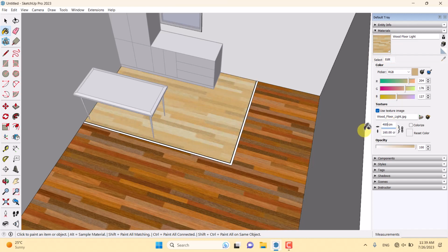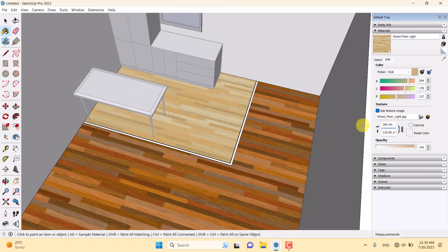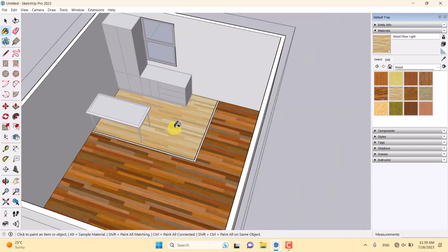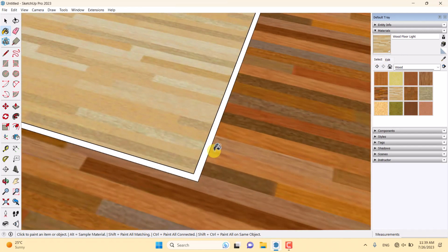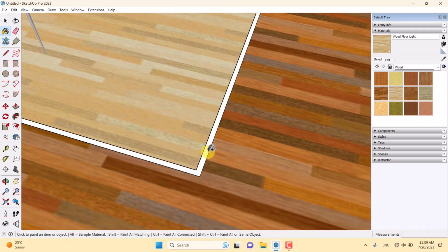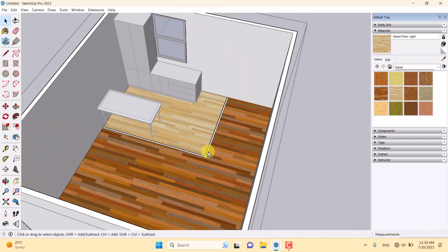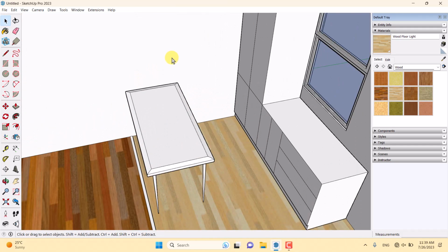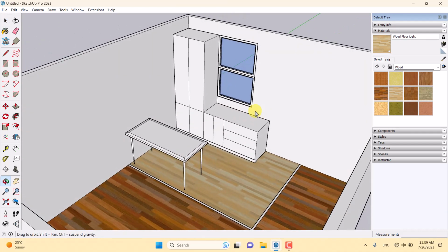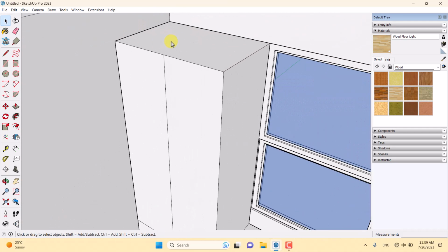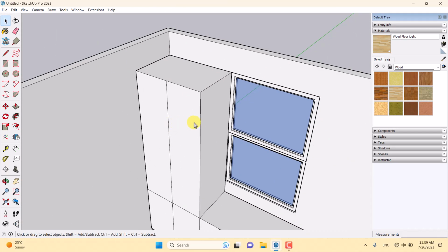Now I want to use the rectangle and draw some rectangle on the blue axis about 3 to 10 centimeter. So how I can move it in this place? Actually, we have different type of modifiers in the 3D Studio Max, like the Swift option or profile. But in the SketchUp, we have some useful option that called Follow Me option.